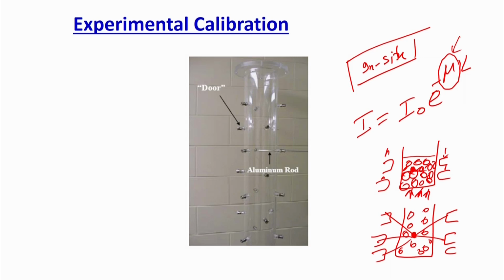So what we need to do at in situ condition, at the same operating condition, is put the tracer particle at several known locations. Now there are several ways, as I said; in literature everyone uses a different method depending upon the operating conditions. Say, what is my operating condition: whether I am operating at a very high pressure or very high temperature, whether it's a gas-solid flow or a liquid-solid flow. So depending upon the type of the reactor and the size of the reactor, different calibration strategies have been developed by different researchers, but the idea is to place the particle at a known location.